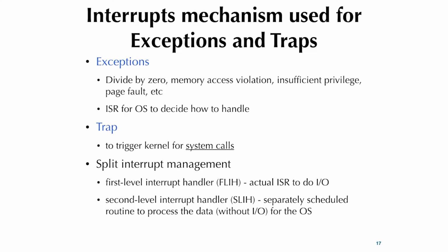So for example, that querying of devices, you could do it in this split phase. First you come in and say, oh, this IRQ got asserted, fine. Okay, I register it, schedule an event, and then I will return quickly. Later, the processor does a context switch and all that, but hopefully this one gets handled as soon as possible, but outside the ISR. Then you can think, okay, query this device. Do you have anything? No. Okay. Do you have anything? Yes. All right. And that way you do that outside the ISR instead of inside the ISR.